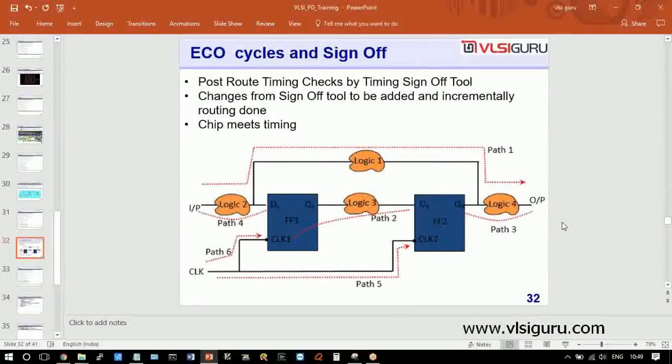Same way, after you finish your routing, you cannot directly give it; there are a lot of problems. You have to call somebody who can certify that my physical verification is fine. The tool is called Calibre. My timing is good: the tool is called PrimeTime. My logical equivalence is good: the tool is called LEC, Cadence. My IR is good: the tool is called RedHawk, Apache. All these people will have to tick, tick, tick. Only then is the GDS of good, worthwhile quality and can it be given for manufacturing. Coming to the ECO part, the timing part of it: if the tool does not show any violation, you take it to PrimeTime and it starts seeing violations.